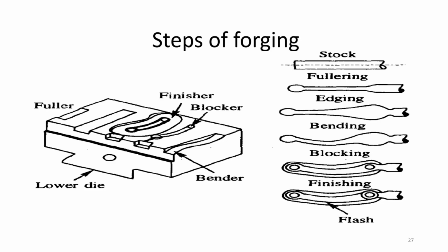They increase the area of the austenite part. When you draw your phase diagram for iron and carbon, and then for iron and nickel and iron and manganese, this austenite area keeps on increasing, and it comes to even room temperature in some cases. So some steels can have austenite at room temperature as well.